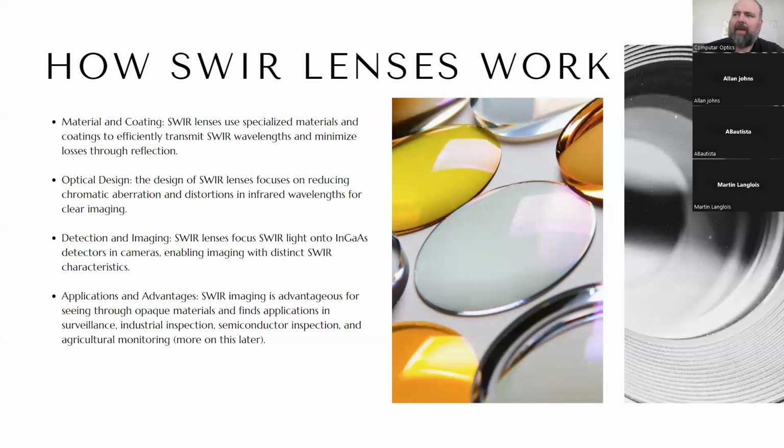Next, the application advantages. SWIR imaging is advantageous for seeing through opaque materials. That's why you use SWIR for your inside-the-lab type applications. SWIR is very useful in seeing through plastics, your hard plastics. So a lot of fill level and height level detection applications. Maybe detecting if the right product is in the right container without having to actually open the container. Think of it almost like an X-ray. It's definitely not replacing X-ray in the food and packaging industry, but it's a very good complement to X-ray.